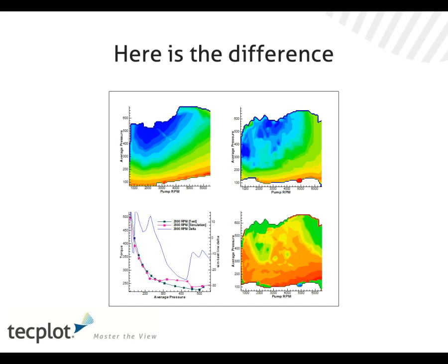And the other thing is you have to be very aware of any sort of stretching within the grid, because a lot of these interpolation techniques that we have are sort of a uniform spacing along the line, and sometimes you have very fine spacing near the wall. Now, the one you did with the contours actually will vary the spacing according to the underlying grid structure. So that's a good way to go if you want to retain the spacing that's in the underlying grid structure.